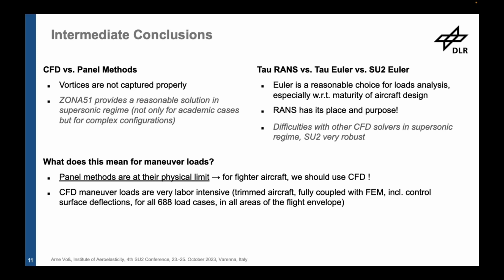So first of all, we can say that aerodynamic panel methods are definitely at the physical limit here, and that for fighter configurations or any other configurations that have a vortex-dominated flow, we definitely should start using CFD as early as possible in the design stage.